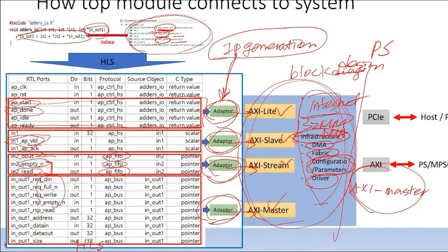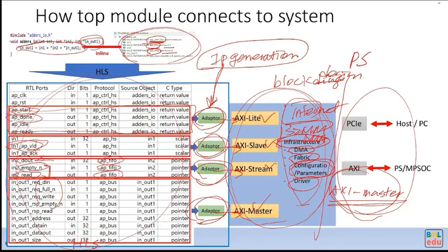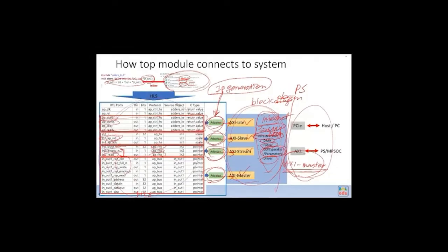So now you have the steps of the process from the kernel function to how you can communicate with the host. That's the argument. So when doing the HLS design, the function argument is a very critical part, and it relates to the chapter on I/O interface. I will explain in greater detail in a later chapter.